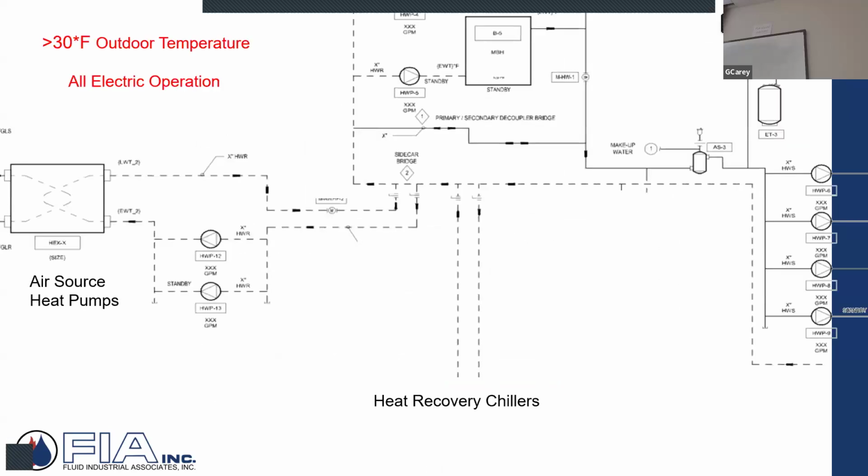And so we kind of go through some scenarios and we say, hey, look at when the outdoor temperature maybe is greater than 30 degrees and the load, whatever the load is, maybe my air source heat pump and maybe even part of my heat recovery chillers can provide some capacity and I won't rely on my boiler plant.